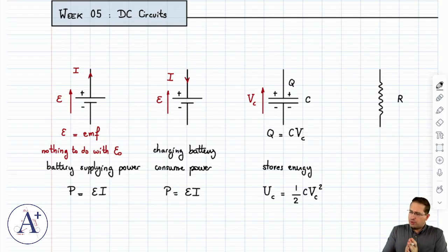Resistors are new. Okay, so resistors are a two-terminal component. There's two terminals that are conductors. They're just not great conductors. So they will let current through, but they will have a voltage across them that opposes the incoming current. Basically they make it hard for current to flow through them, and the voltage that exists across them is proportional to how much current comes through.